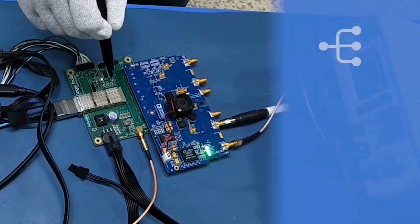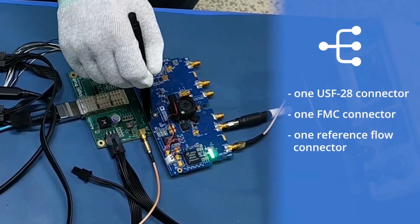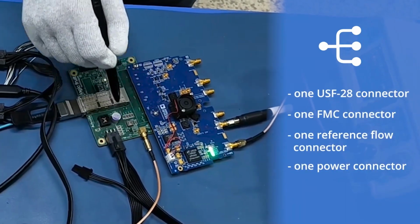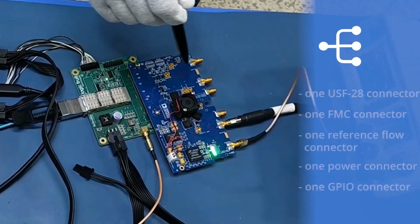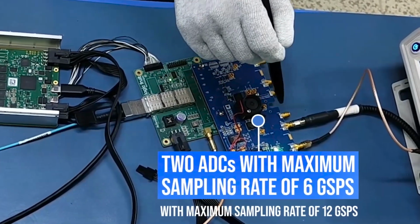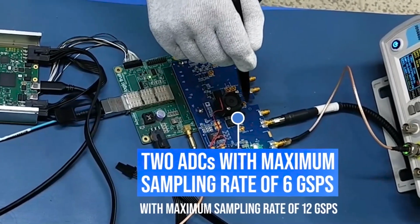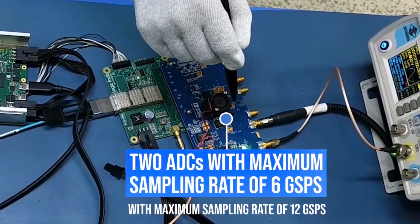Now this adapter board has one QSFP28 connector, one FMC connector, one reference clock connector, one power connector, and one GPIO connector. And this eval board has the AD9082 IC, which has two ADCs with a maximum sampling rate of 6 GSPS and 4 DACs with a maximum sampling rate of 12 GSPS, and a clock chip.